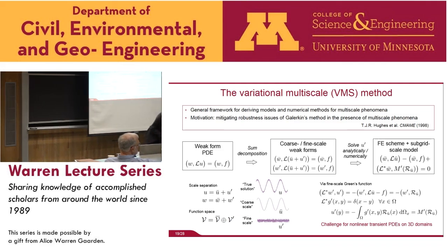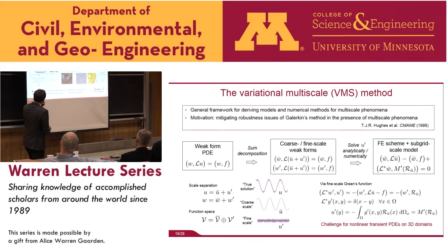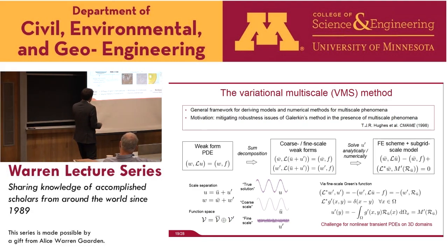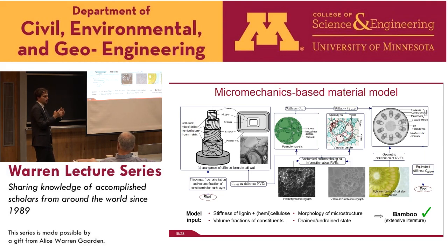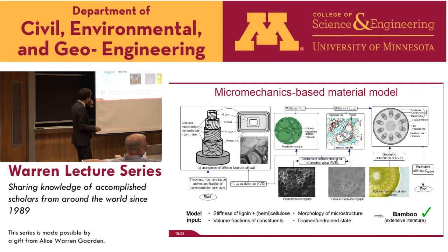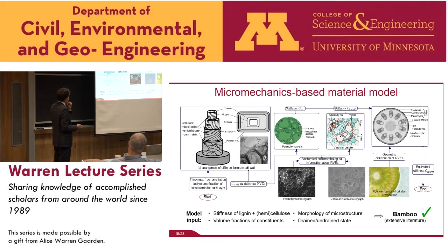That is a very interesting question. Right now we assume that all that transfer is linear up to this point. So in the finite element model at the macro scale, we then allow large deformations. That's why we get this buckling phenomenon. If you go from no material failure to a model that also includes material failure in terms of yielding effects, then these yielding effects are known to be at the cell wall level. So that introduces the problem that you also have to upscale strength.